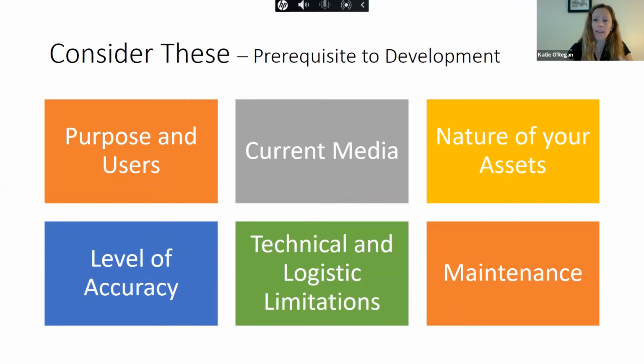So if you can collect GPS points within a couple feet, that's still going to be more than good enough for you to keep track of some of that information. So there's that consideration. More is not necessarily always better here. Correct. It really depends on what you're looking to do in the end. If you're looking for a surface feature that you can find within a few feet, yes, you might not need survey grade accuracy.